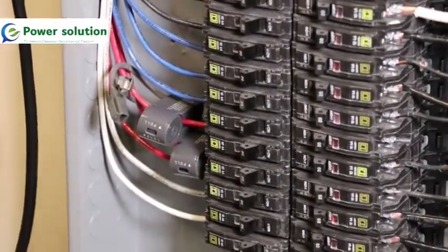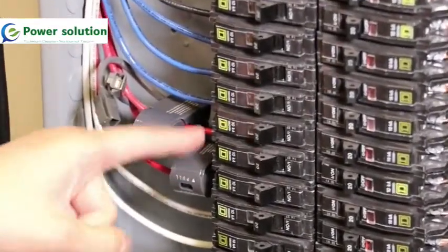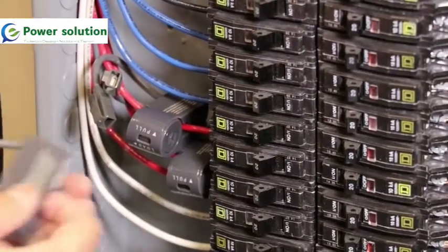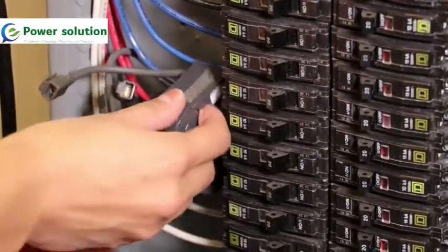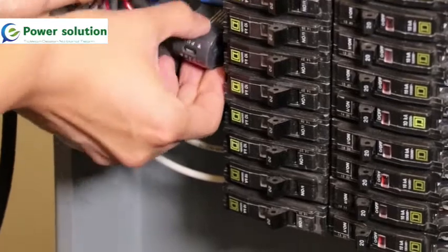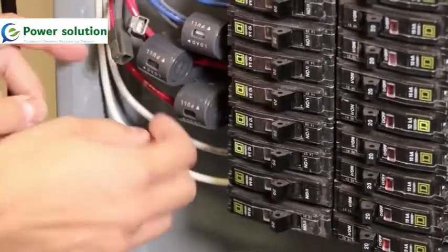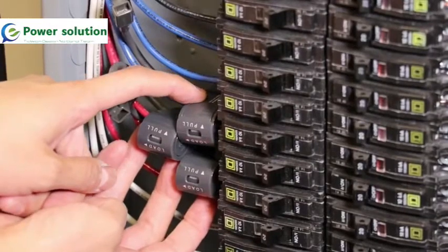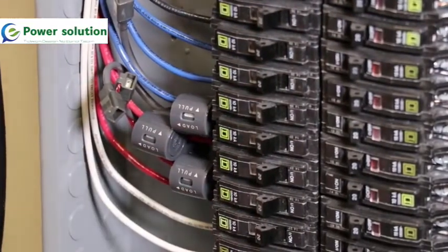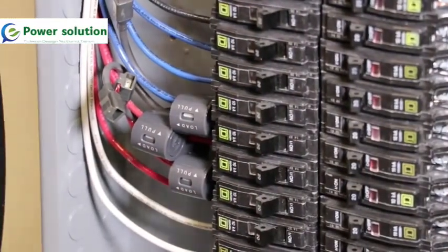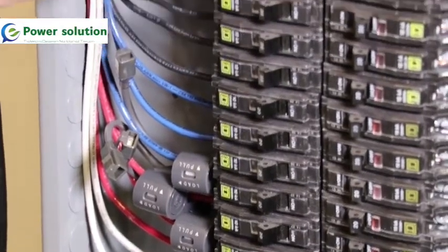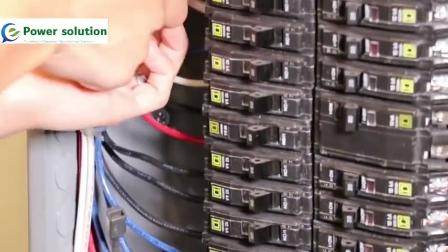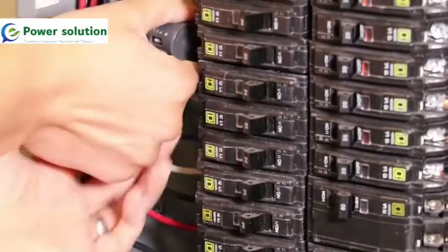In this particular panel, we have very, very thin breakers. In cases where space is required, you'll see it's better to stagger the current transformers so that they fit. In places where you have a little more space, the current transformers can be stacked one on top of each other.